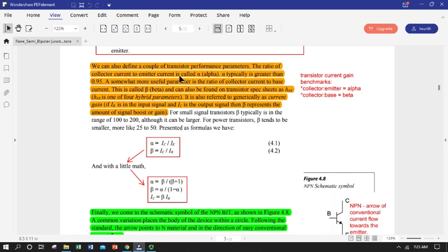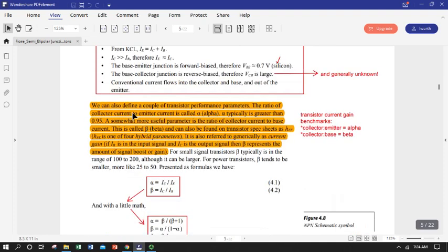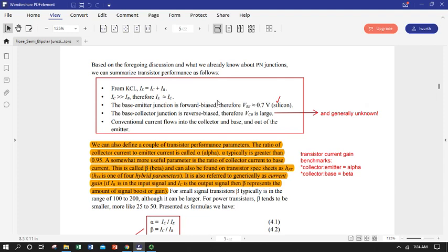In our previous lecture, we went over the material science that makes up a BJT, or bipolar junction transistor. We discussed how it has 3 different layers of semiconducting materials, 2 P's with an N in between, or 2 N's and a P in between. We discussed how the thin, lightly doped base is key to making it work, and how it was different than just 2 diodes back to back, and touched on the concept of current gain, which is what a BJT basically is all about. Then we went on to discuss how Kirchhoff's current law operates, relating emitter, collector, and base currents.